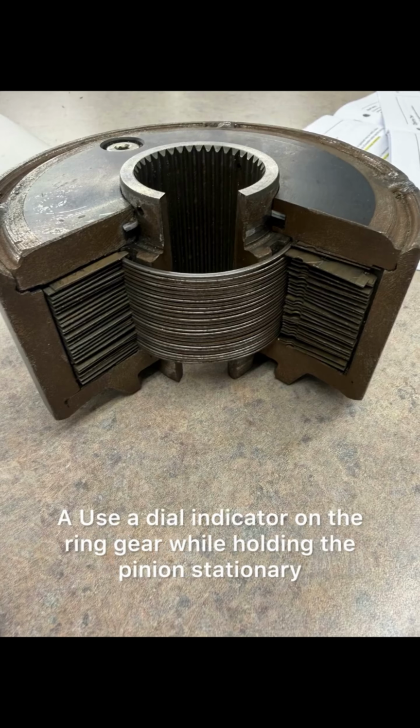19. What causes excessive axle shaft end float? A. Worn C-clip, worn side gears, or worn axle shaft. 20. Why does noise disappear when turning left? The right side bearing is unloaded and likely worn. 21. Why would a differential lock up in tight turns? A. Wrong oil in LSD, or seized spider gears in open diff.